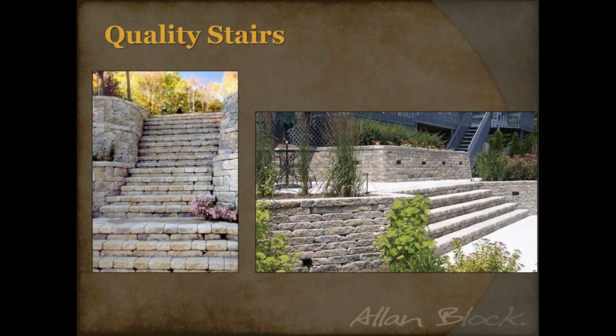And this is a great example here where they're just taking some terraced walls and feathering it out, easy for me to say, but feathering that here, so that way it's not just one consistent stairs where it looks like it gets taller or longer and longer as you move up. They're using the terrace to kind of reset and look a little bit more like an hourglass, which is a great way to hide when you do your layouts in your wall.